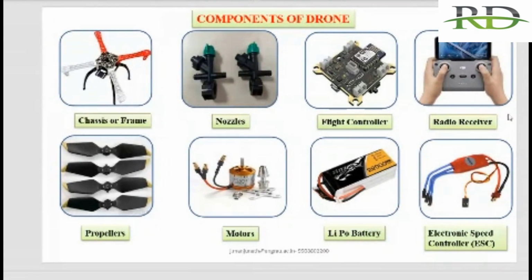This is a LiPo, a lithium polymer battery. Now we are using lithium ion batteries. This type of battery is 22,000 milliamp hours and 16 amps. Each battery can be recycled maybe 2,000 times, and the lifespan is approximately 3 to 4 years. Each pair of batteries costs about 24,000 rupees. Like this, we can fly the drone only 10 to 15 minutes.